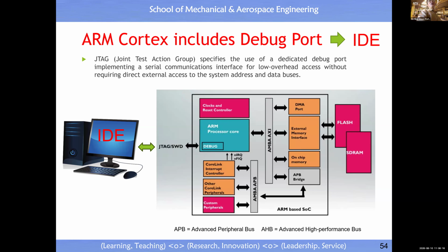You have forgotten to download the modified version to the microcontroller again. Always remember, whatever you modify, recompile it, download it, then execute it. If you just modify and then execute, nothing happens, because you have not yet compiled it and you have not yet downloaded it into the microcontroller.